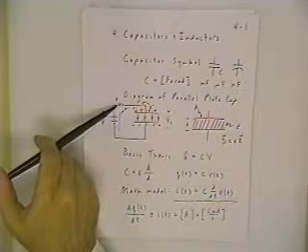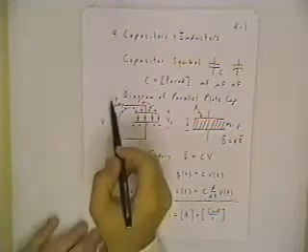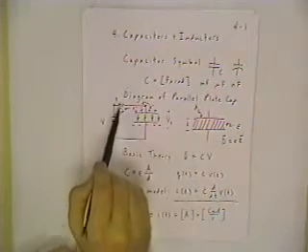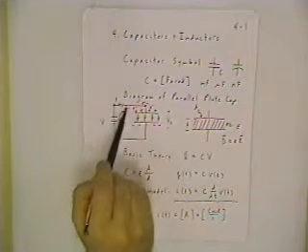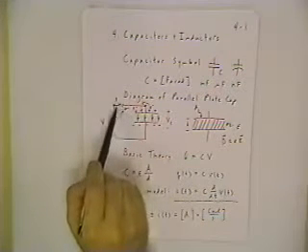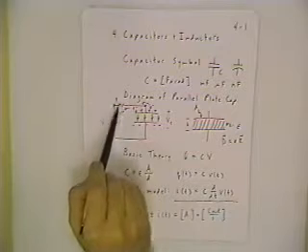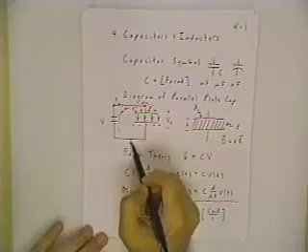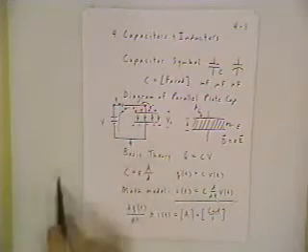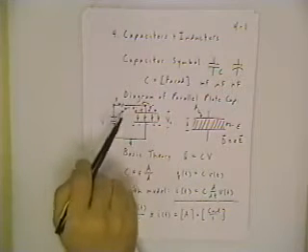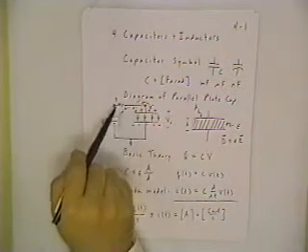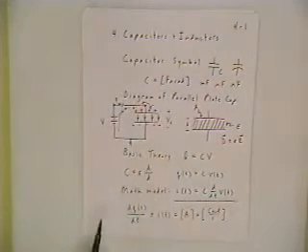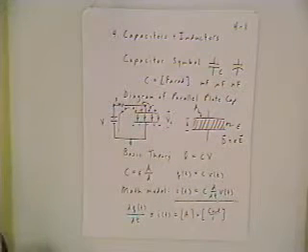The only way this resistor has any current flowing through it is if there's a potential difference across it. So comparing this node and this node in the circuit, if that potential difference is zero, there'll be no more current. And if that current is zero, then the voltage at this node is equal to the voltage at that node. They're both equal to V. And that shows that with respect to the ground node here, the capacitor has fully charged to V volts. Until that fully charged condition happens, you still have current in the resistor, and that means that there are some expressions we can come up with for calculating the current as a function of time. And we'll get to that in turn.